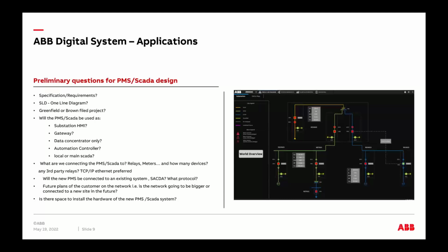So when you start now, you're done. They come to you as an HMI or power management system or power monitoring system or a SCADA design. They want you to do SCADA for them. You need to start asking questions. If they have specification requirements, it's good. Take a look at it. Maybe you could give them some advice if you see something that doesn't seem right, right? Maybe they have a single line diagram already for you. Here's my single line diagram. Please make it an HMI for me.